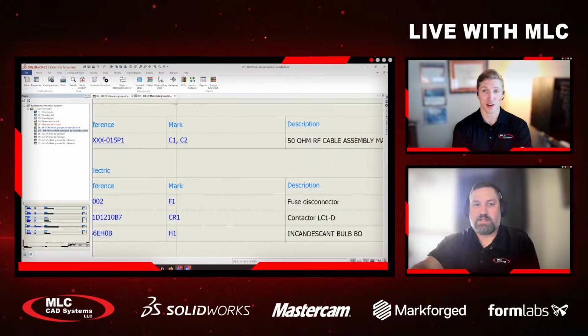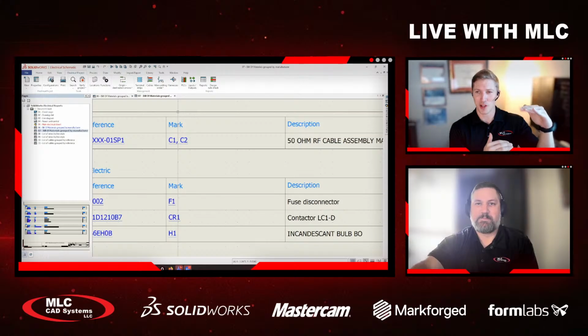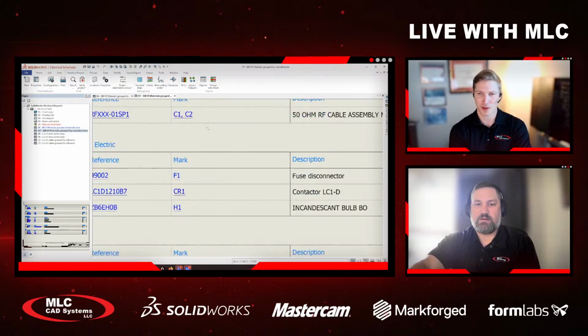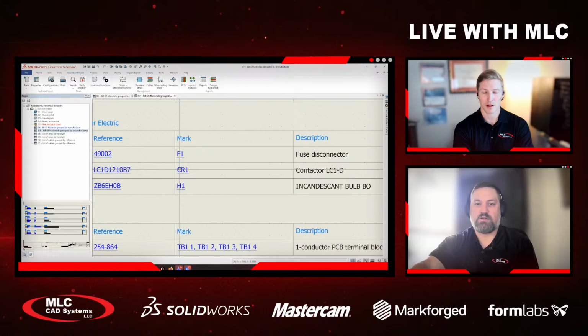And I guess that's... Now, I want to take, across, sorry to interrupt, but is that across sheets? That's fine. Because one of the things with electrical, you have so many sheets here. Does it show if you use it on like three different documents, I guess I should call them? Yeah. So like CR1, if I go to this one, you'll see that there's three different symbols that represent it. On page 4, column 2, row 17, page 4, column 1, 11, 4, 2, and 18. Whoa. So these three symbols all are representative of this one physical device of CR1.